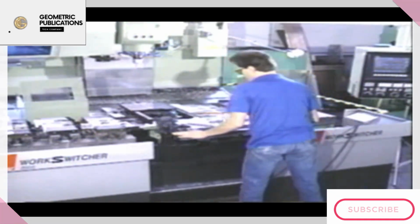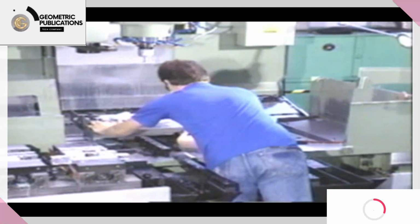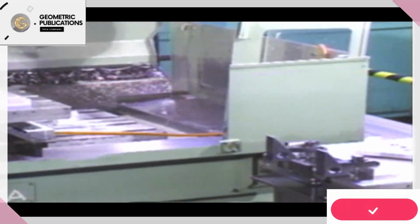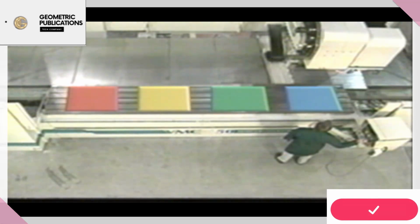Work changing represents another opportunity to get more machining done with less wasted time. Saving time by setting up fresh workpieces while the spindle is cutting is the goal. Work changing is accomplished in a variety of ways. A long machine bed may permit fixturing several workpieces with parts run sequentially.